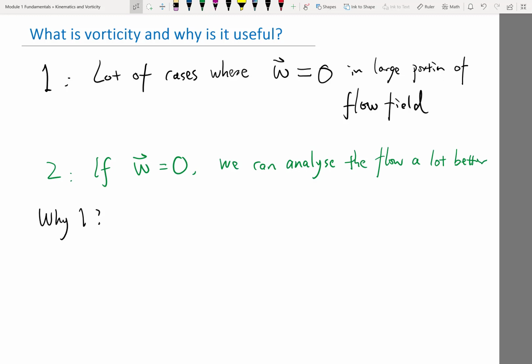And we are going to see that if there is no vorticity to start with, which is the case if you consider an airplane flying in very quiet air where there is no turbulence, then the incoming air has no vorticity because it's a uniform velocity, depending on which frame of reference you use. But in both cases, you have no vorticity, because if you add a constant speed to the flow field, it doesn't change the derivative, and the vorticity only depends on the derivative of velocity with respect to x and y. So no matter what translational frame of reference you use, it doesn't change vorticity.